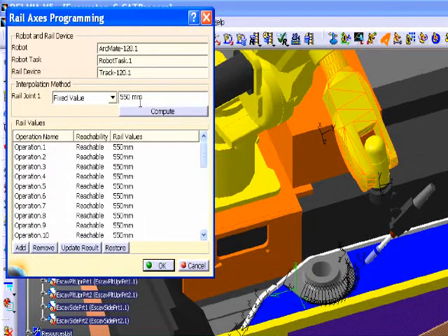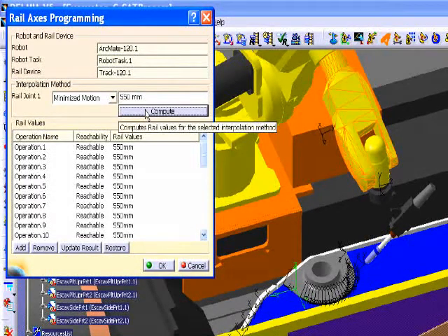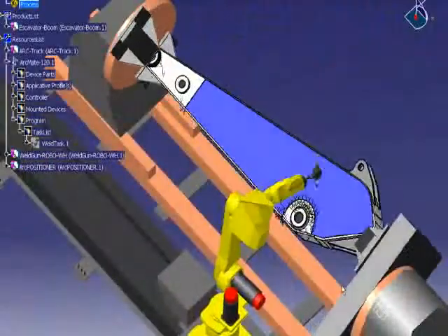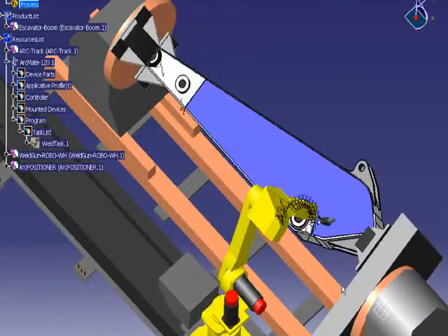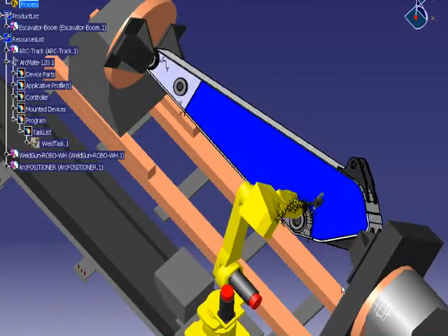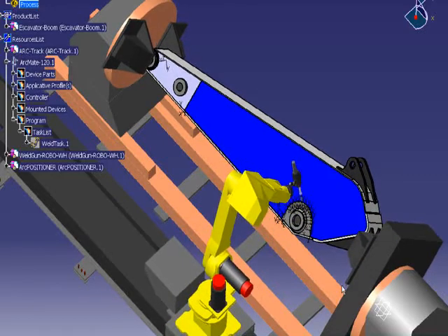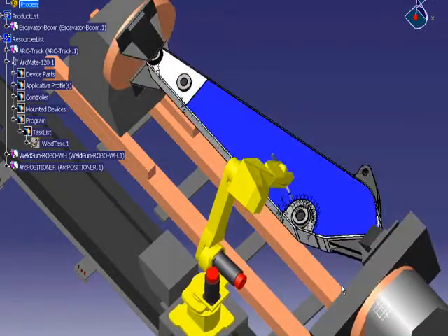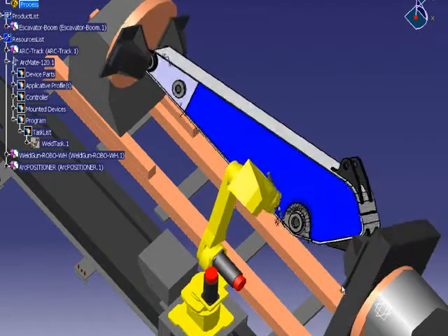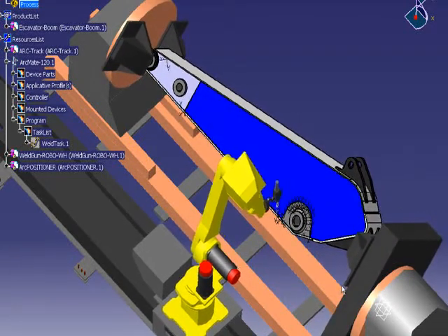The ideal arc weld is as flat as possible. Molten metal flows with gravity, and the part positioner keeps the weld where it belongs. And there are several options when programming part positioner values. You can program them flat, vertical, or horizontal, or you can define the position. Once the system calculates the values, it will tell you if the welder can reach all the points in the path.